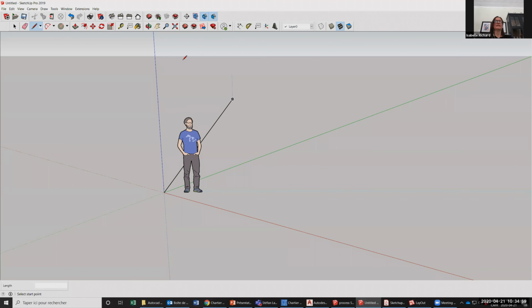So let's say, for example, I'm going quickly, but I'll go over the tools afterwards. Go back to the tools. I want to measure the line I just drew. I just click the first point and then the second, and you see at the bottom part that my line is 69 feet and 9 and 5/16 inches long.